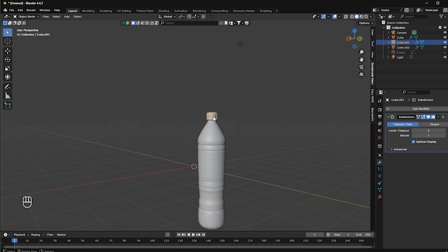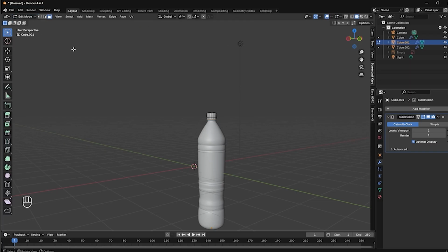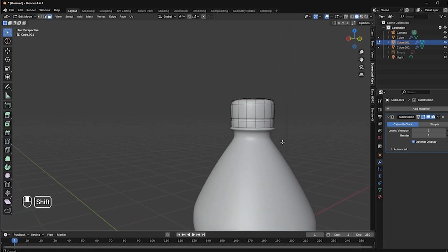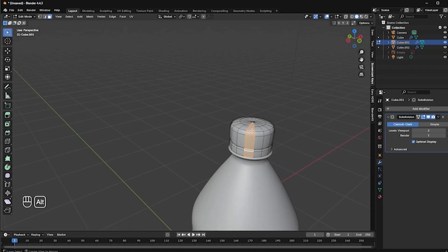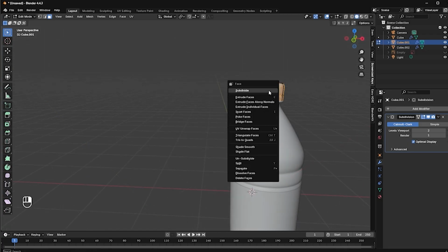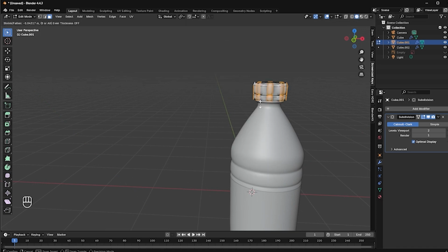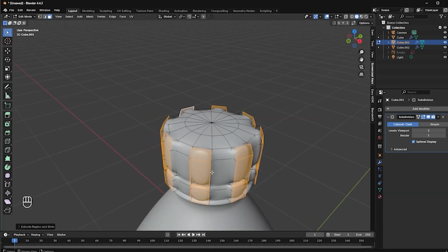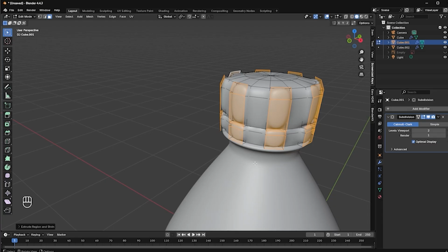First I am going to select the top surface of it. It was in the object mode. Excuse me, it was in edit mode. I am going to select these specific parts. I hold Control. I am going to deselect these items. Okay, so I have selected these ones. I will select Extrude along normals in the Fix menu and give this area a boot shape. So it looks like a boot, okay, and now I can also add a little bit of inset.